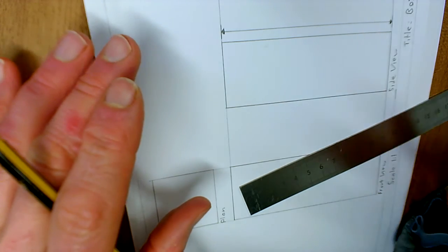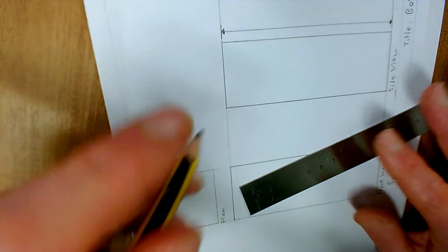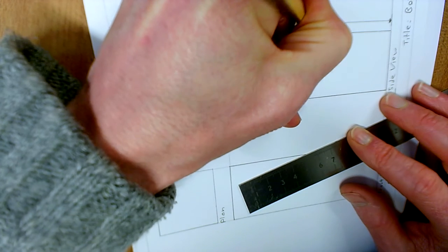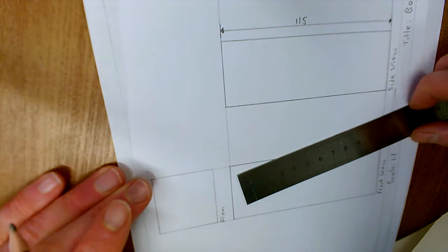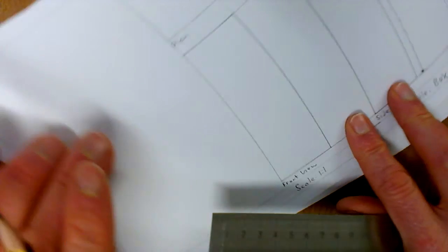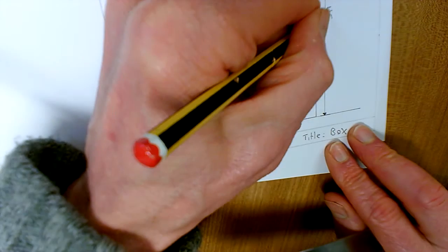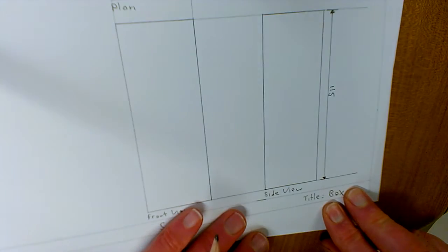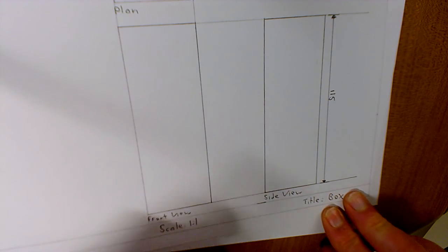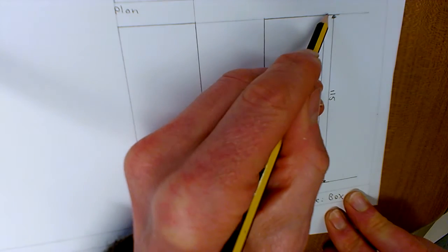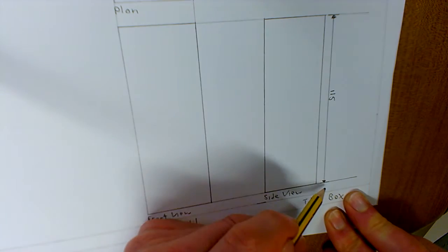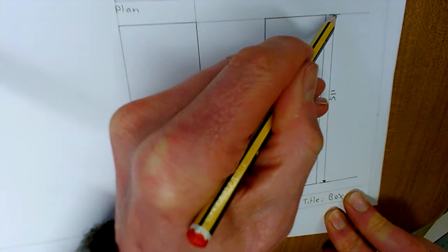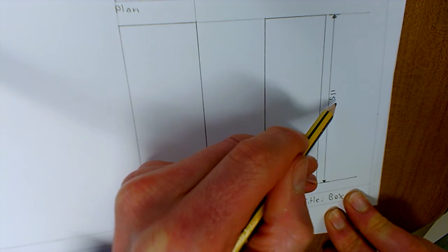Remember, we are working in millimeters, so it's always going to be millimeters. So we're going to just put 115. You do not have to put millimeters. You just have to put the figure. It's taken as millimeters unless stated. So again, you can see it is also running down the line. You can see the two leader lines at the end, which are where you're measuring. Your vertical line, your arrowheads touching the leader lines, and then your dimension in the centre.